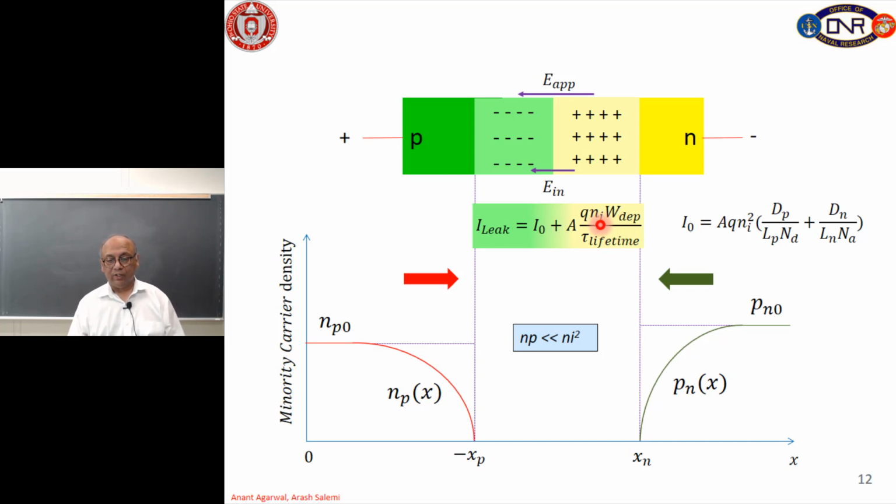I think it is good to explain at this point that both silicon carbide and gallium nitride are wide bandgap materials, and as we had explained in the first lecture, higher bandgap means Ni is 20 orders of magnitude smaller than silicon. So, Ni in silicon carbide is almost negligible, which means that the leakage current to begin with would be very, very small for comparable lifetime in silicon carbide. And that means now we can increase the temperature to much higher values than what is possible in silicon, because Ni would rise exponentially with temperature, but since it is so low to begin with, it will take much higher temperature to get a substantial leakage current. That is why the wide bandgap materials are called the high temperature semiconductors, because leakage current is negligible at operating temperatures.